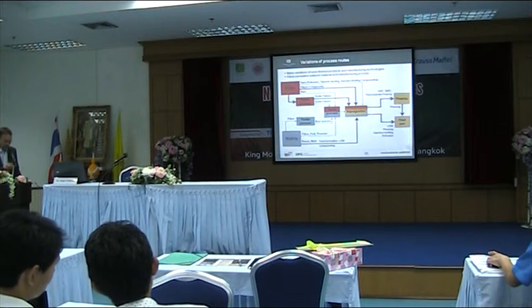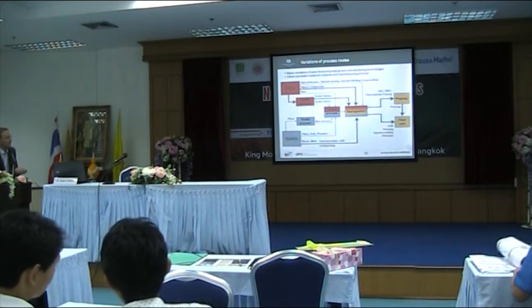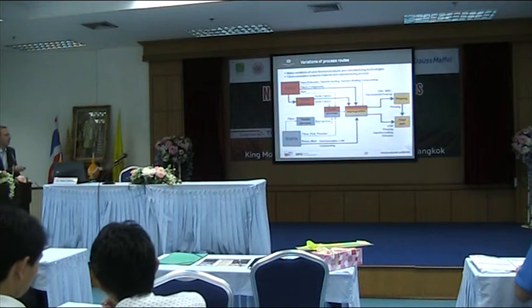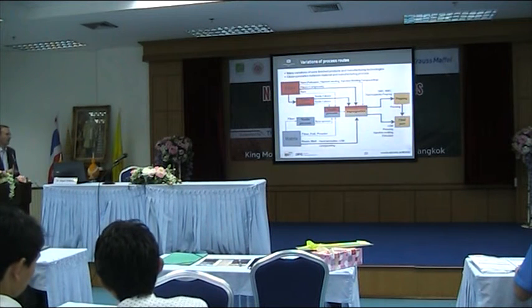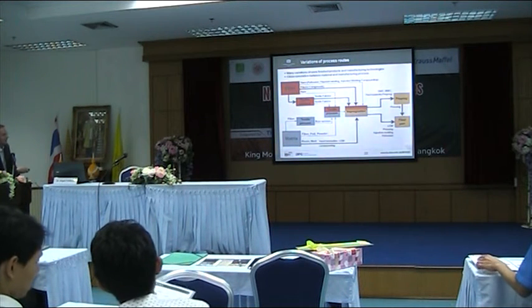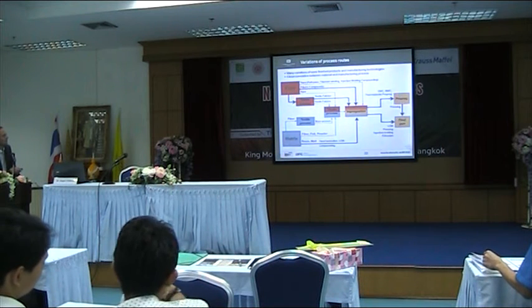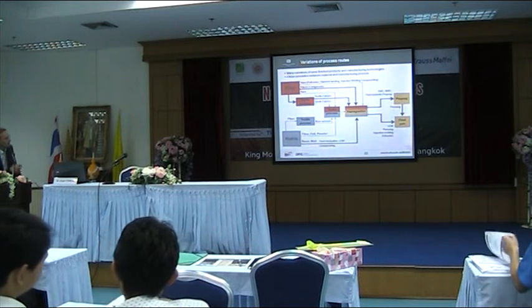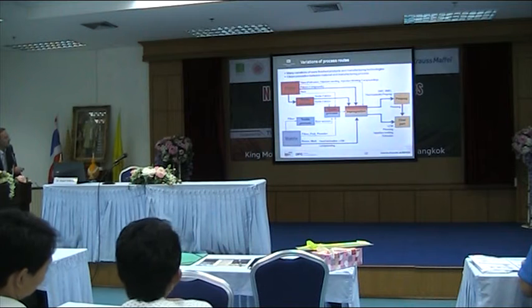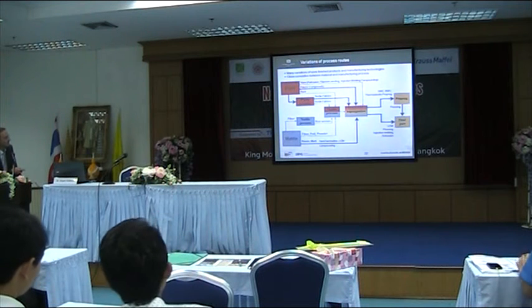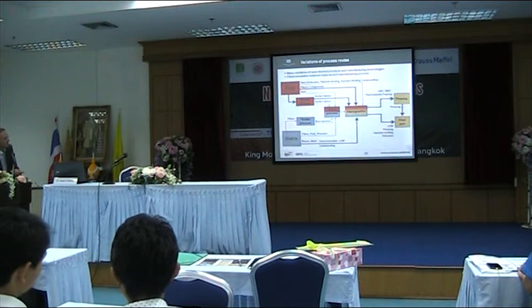And now just imagine which production path you can go, and you have a lot of variations you can use to go to a pre-preg. And it's the end of the final part for thermoplastic processes. So, for example, the fiber can be really single fibers, can be a yarn. You can go directly into the textile process for weaving, or you can directly go into the impregnation of the fibers with the matrix.